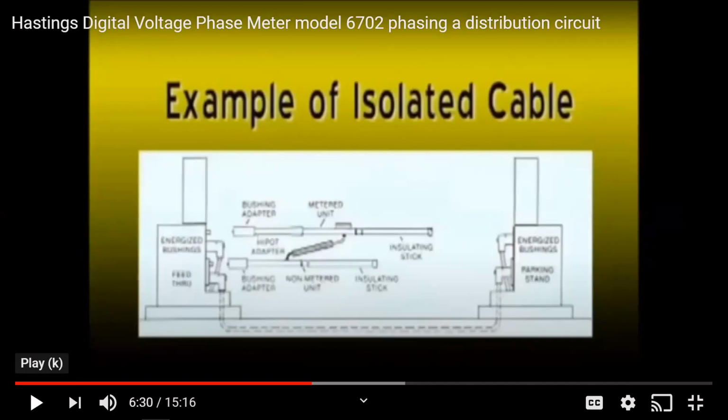Okay, so what does he mean when he's talking there? What does he mean by isolating the cable on the far end? Open the circuit. Yeah, in what manner? Just disconnect it from the transformer. Yeah, so if I'm coming out of the transformer 1 and it comes out on the B side and it goes into transformer 2 on the A side, what do I need to do with the transformer 2A wire? Disconnect it, and you can put it on a standoff. We saw those standoffs yesterday. Disconnect it and put it on a standoff.